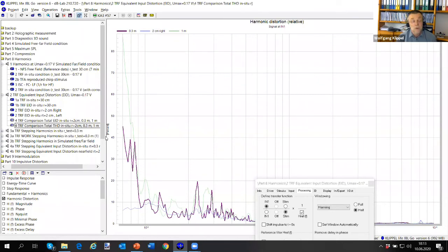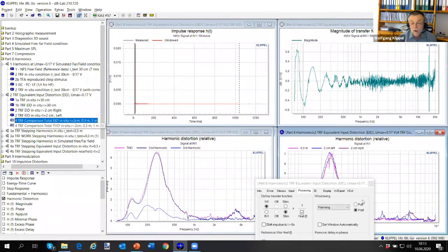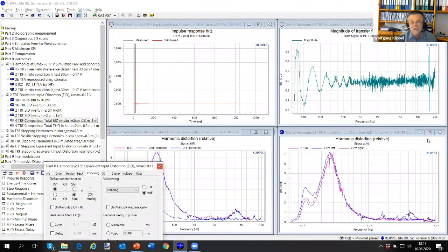In other words, if you are doing harmonic distortion measurements, you should try to get relatively simple curves. Then you are doing good harmonic distortion measurements. And what does that mean? Measure in the near field. There's not a big need to go into the far field. It's only post-shaping. And move the microphone around a little bit, and then you will usually see quite nice flat curves, a little bit different, telling you something about the modal vibration and other things.